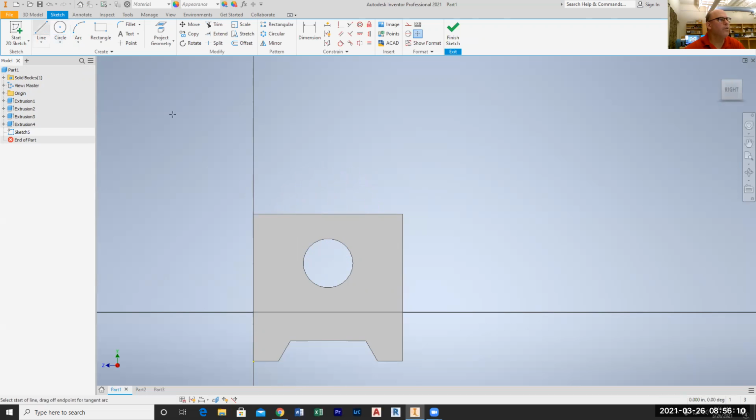Let's just do this. I'm going to draw a line from the center point here, and this is going to go down 0.75, right? 0.75, enter, enter. Okay, so now I'm going to go ahead and draw a circle from here, and it's going to be right to there. That's actually 1.5, so I just click that. Now I need a line that goes from here to the edge of this tangent. See how that little tangent thing comes up? Let's click that. That's that little tangent mark. So that means that that's touching the outside edge of that.